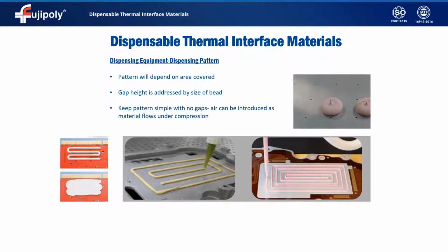Questions regarding the optimal dispensing patterns come up regularly. Is one pattern better than another? Is a bead better than a Hershey Kiss? Do I need to cover the entire component? The area the TIM is intended to cover and the thickness of the gap is obviously a key consideration.